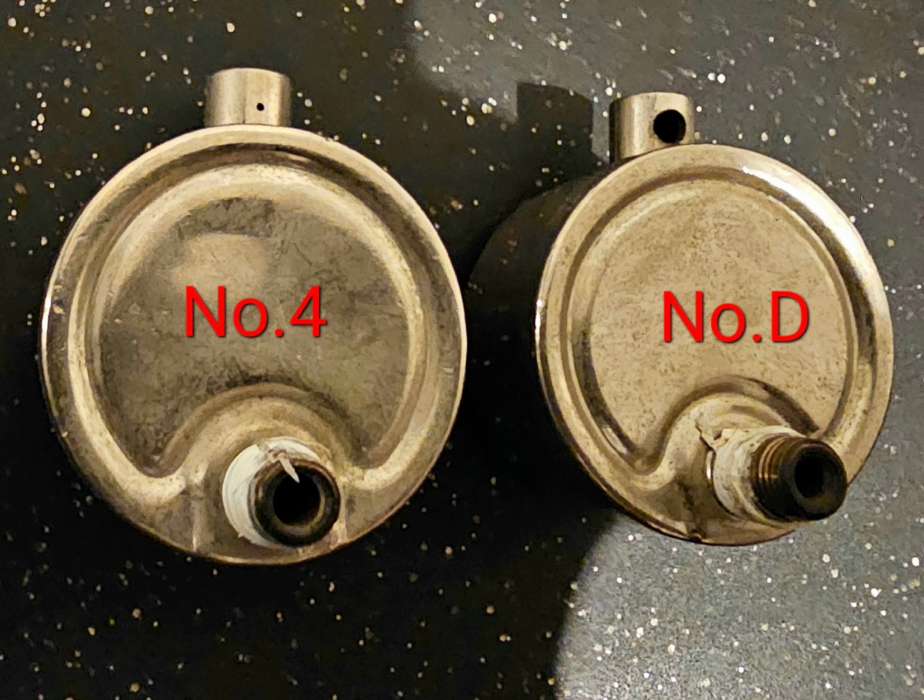In a case where you might have one section of your house or your building heating up faster than the other, you might want to put these smaller Gordon number 4s to slowly vent out those radiators that are heating up quicker. That way you can get the steam to where it has to go, or the harder places, faster. So these are very good for radiators, Gordon number 4.